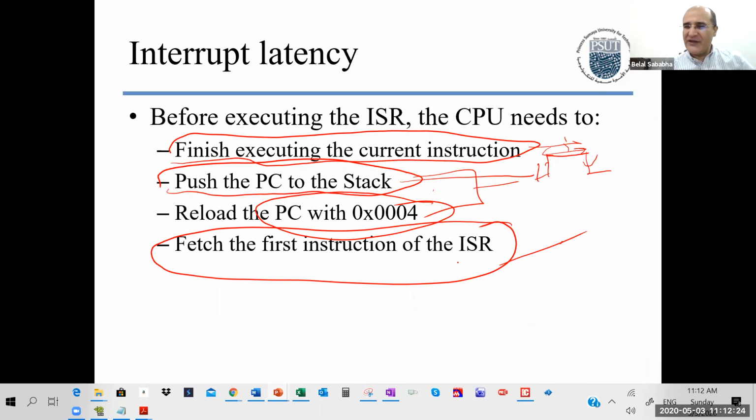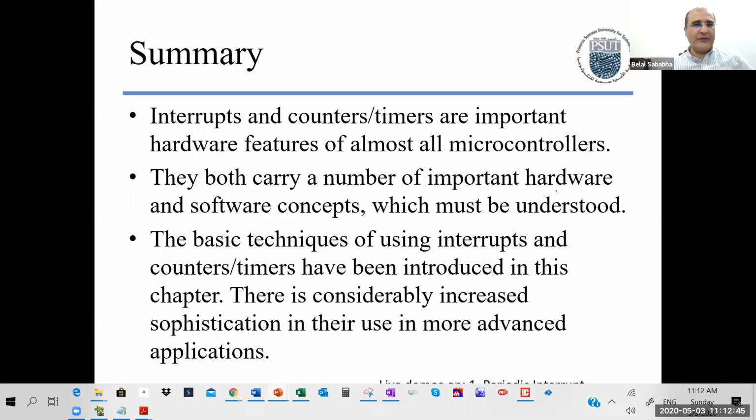You can reset timer 0, for example, and write a 1 here. Okay, then this will go high. Inside the interrupt service routine, you can make it go low and tie this to a scope and measure it if you want really accurate timing.